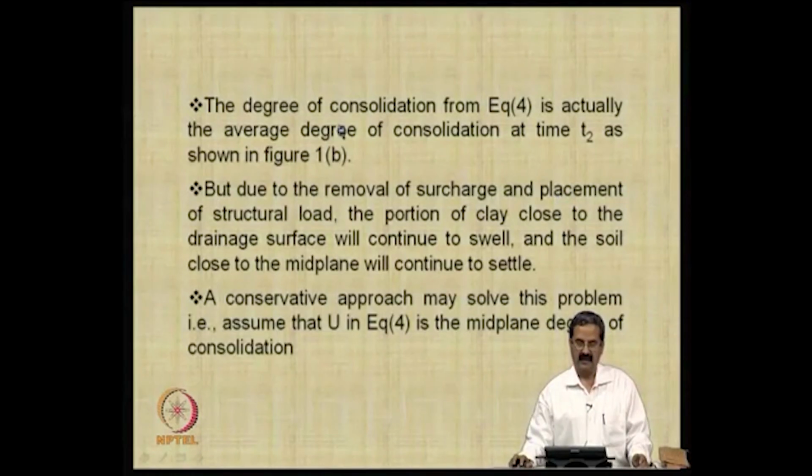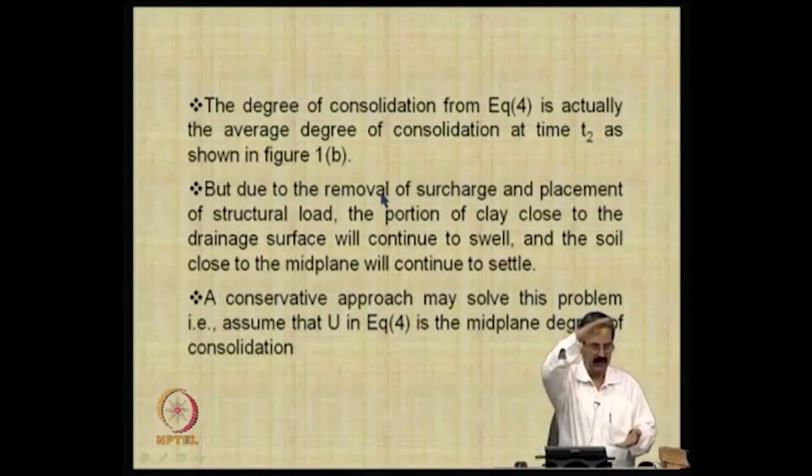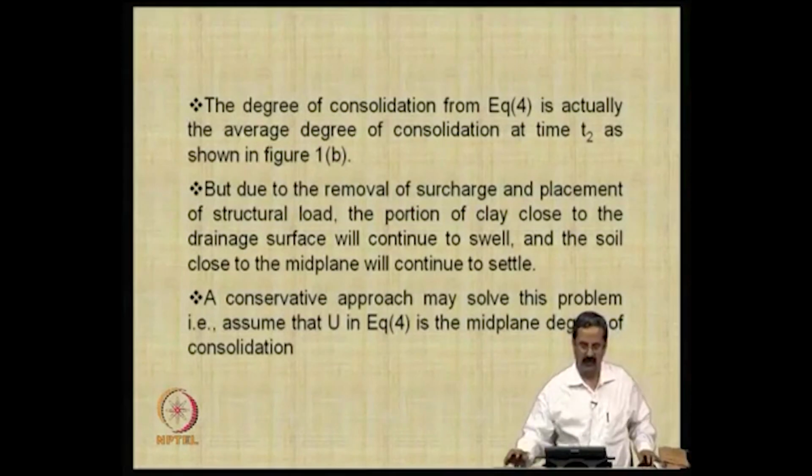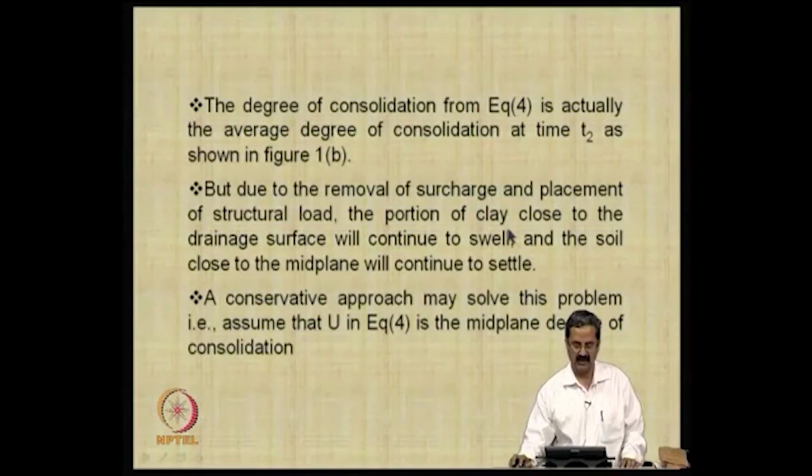Then the degree of consolidation that we have is actually the degree of consolidation at time t2. What we do is that it is an average value. Say you have about 10 meters depth, at some point you are calculating the average value; everything is average. So, when you remove the surcharge and place the structural load, some portion of the clay close to the drainage surface will continue to swell, and the soil close to the midplane will continue to settle.